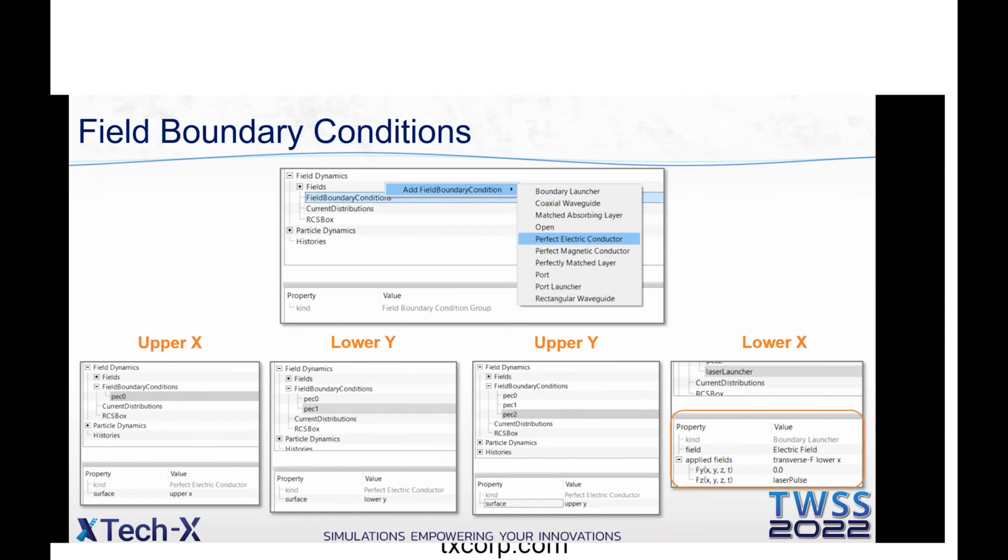Yeah, I'm having a hard time parsing that sentence. But if what you're asking is, are those the only kinds of boundary conditions one can have for electromagnetics? The answer is, actually, we have a few more. We have boundary conditions such as, for example, ports, which allow a wave of a given phase velocity to exit a system and have no reflection coming back in for a particular wavelength. Those ports are very efficient for what they do, and they take only one cell to implement. We also have matched absorbing layers, which adiabatically damp the wave as it leaves so that there are no reflections.